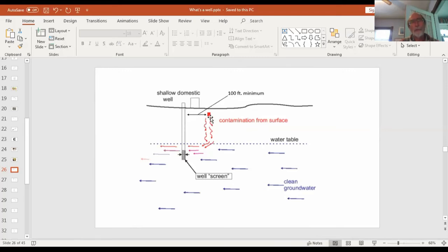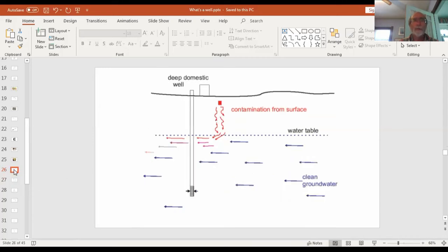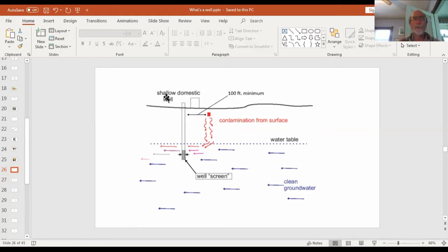So in this particular configuration, the contamination has descended from the septic tank. It's now hitting the groundwater table. The groundwater is moving from west to east, and sweeps it down gradient, where in this case it probably is picked up by the well. DEQ requirements, when one does an analysis of the impact on aquifers, suggest that this first 30 feet is the critical zone in which one is most likely to see contamination from any surface source. Now, okay, so here's a shallow domestic well. Let's continue our story.